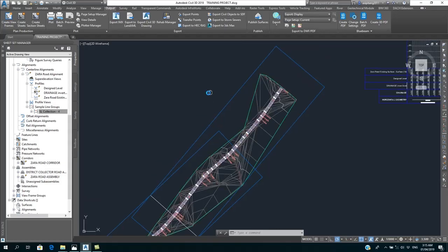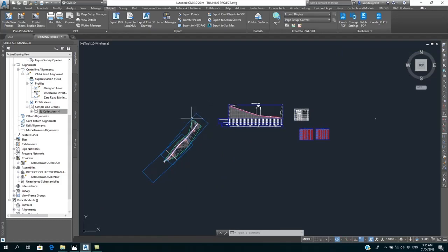You can easily modify any design informations and everything will update itself. And you can do your final production in the Civil 3D interface. So we've done the conversions. Then just in a moment, I will show the procedure of converting and taking these informations to Infraworks and work directly from Infraworks for the next sections.